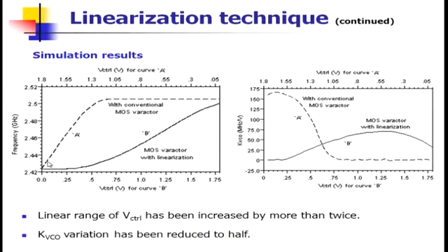Now if you increase the tuning range, what is the advantage of that, I am saying. Suppose this is with the MOS varactor tuning without that common source stage. How would you say that? This is the control voltage, this is the frequency, like that. So this is a very steep del V del C, clear? It is a steep one.